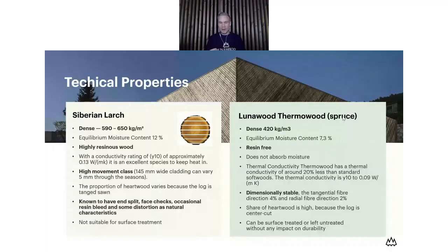And when talking about surface treatments, again, Siberian Larch is not suitable for surface treatments. But like I said about the resin freeness and the dimensional stability, ThermoWood is a really good base for various coatings. It can be surface treated or left totally untreated.